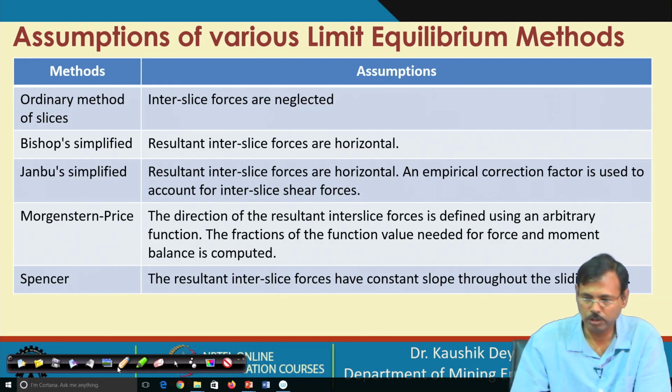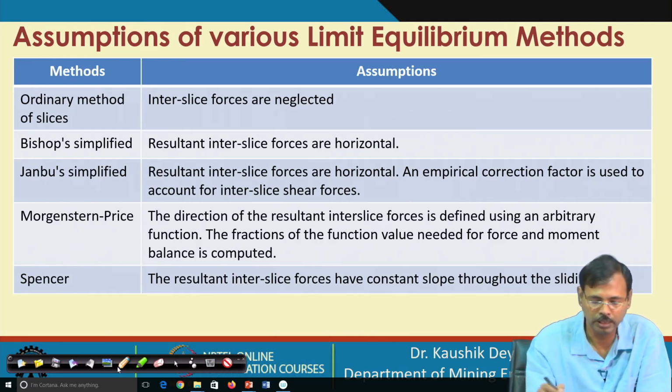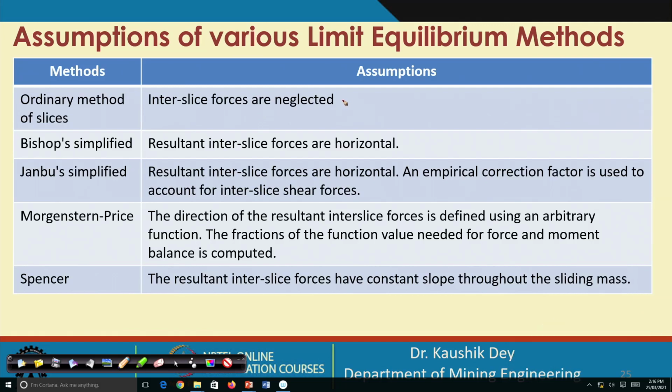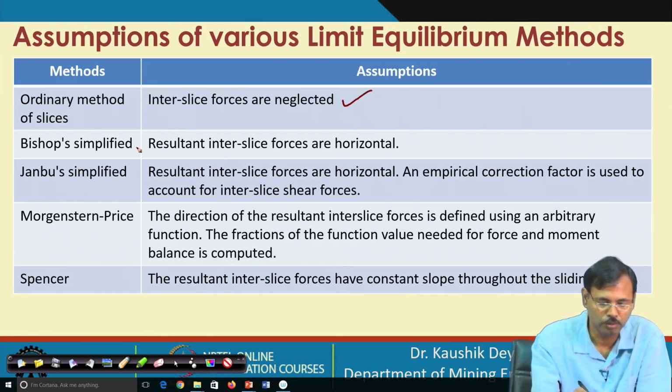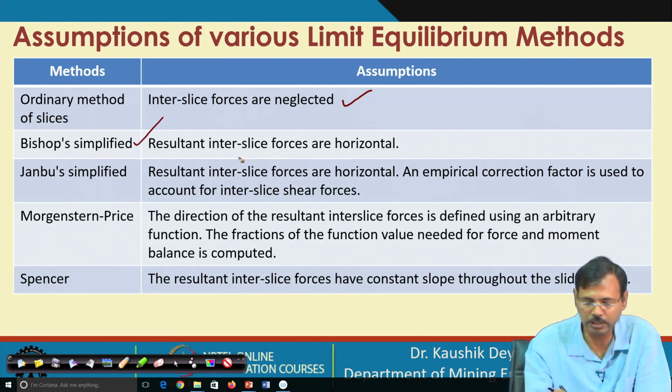Now, in the limit equilibrium method, the assumptions are made like this: interslice forces are not considered in the ordinary method. When the Bishop method is used, the resultant interslice forces are considered horizontal.